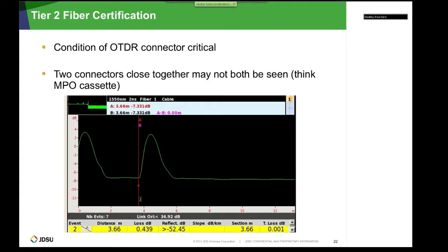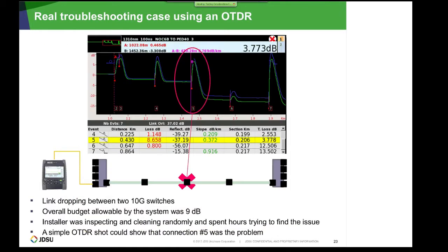Okay, this is an example. There are some traps and pitfalls in OTDR measurement. It is necessary to take into consideration that there are some limitations of OTDR. Generally any OTDR has a limitation, called the event dead zone. It means you are not able to detect two optical connectors which are too close to each other, where too close means the distance between the two connectors is shorter than the declared event dead zone of the OTDR. You are not able to see the second optical connector because it's hidden by the reflectance from the first optical connector.